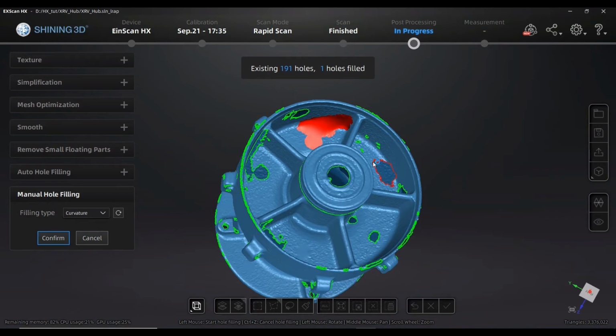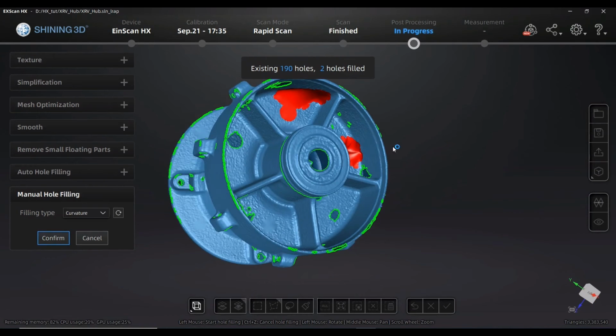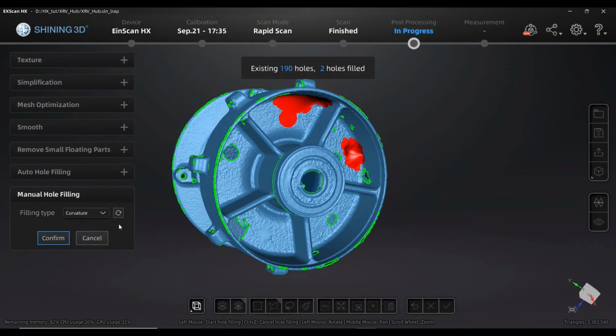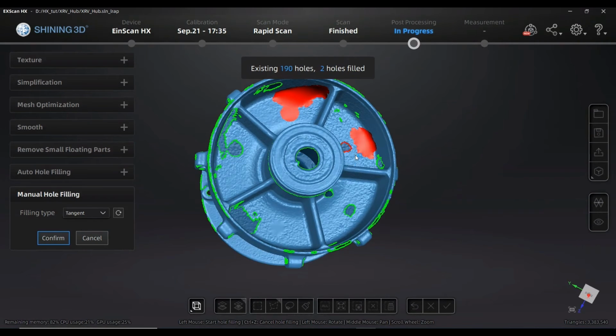What can happen is that in very, let's say, unsteady surfaces like here, bended edges, scanning errors, whatever, can lead to some very unsteady surface, and maybe that's the reason why they are not using it by default. So in this case, if I have that kind of strange behavior, I can go back to tangent or straight to see if it's doing a better job, and it does actually. So this is some kind of try and error procedure to see what is good there.